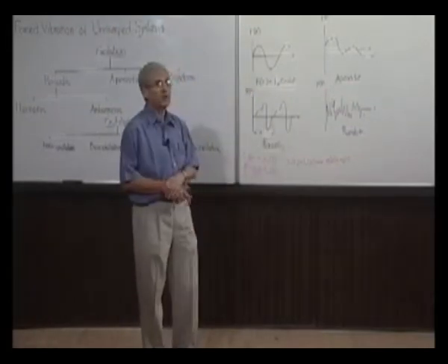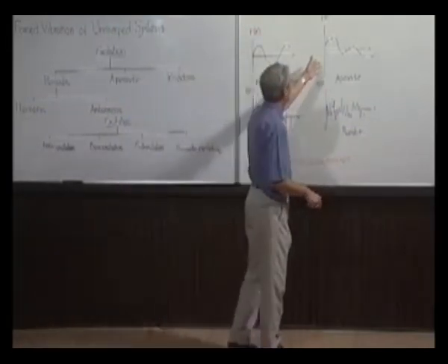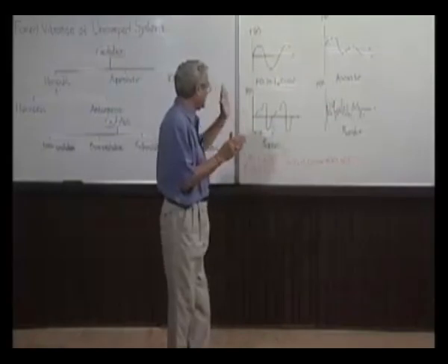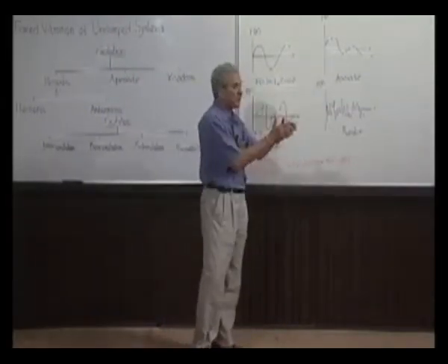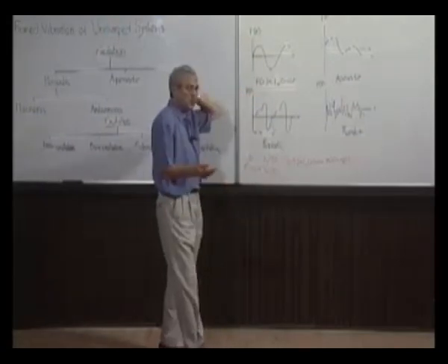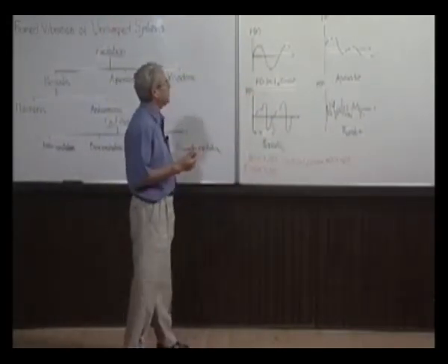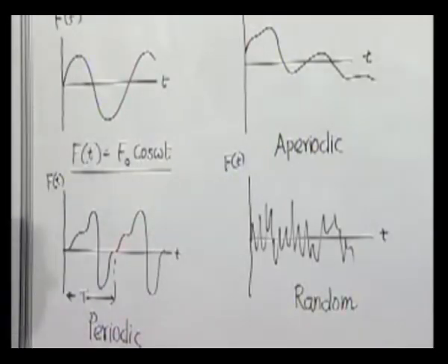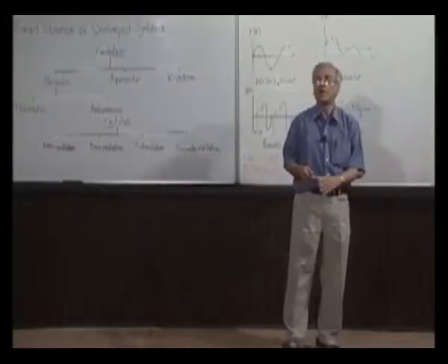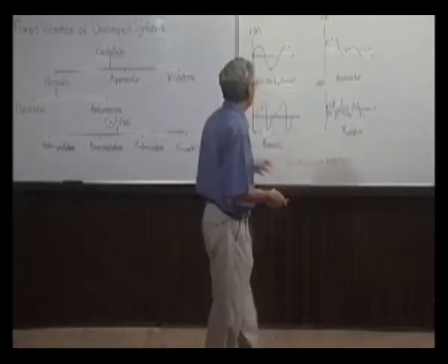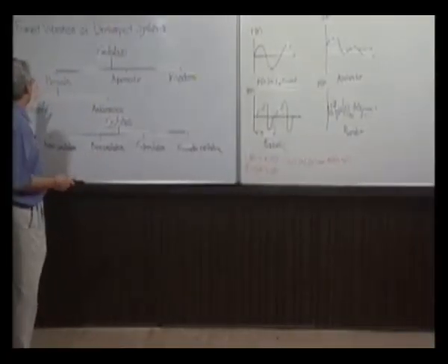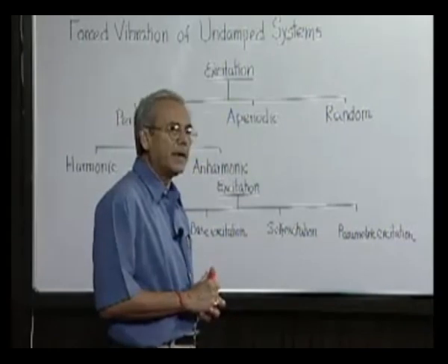Even aperiodic functions of time can be represented in terms of an infinite Fourier transformation, and there of course it will not be discrete frequencies, but the frequency spectrum will be continuous, and we will see such cases. But the conclusion is that even this problem can be solved using the result of the system's response to a harmonic function, because this can also be represented in terms of harmonic functions of time using Fourier transformation. So if we are handling linear systems, knowing its response to harmonic functions of time can give the result of any type of forcing.